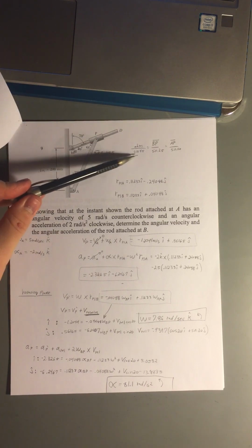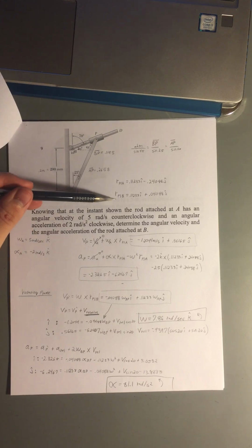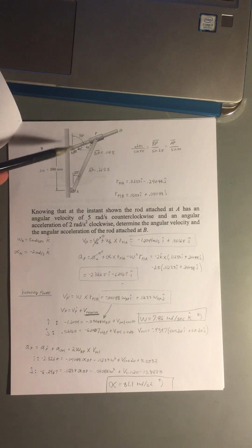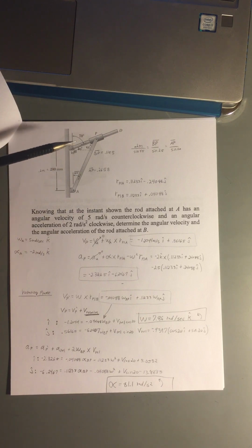And so I used the law of sines here to calculate those, and those are the answers I came up with there. And then once that was done, I know in the formulas we're going to be using, we also needed to calculate these two as well. And so just looking at the geometry here and using trigonometry with these angles, we're able to find out what P with respect to A is and what P with respect to B is, because we're going to need those as the problem goes on.